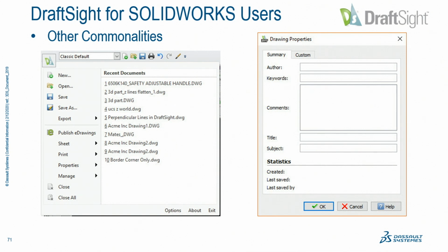What I was going to say about the tables: if you have AutoCAD Mechanical, and you're using the smart bill of materials and stuff like that, currently that does not transfer. So if you want to bring that stuff in, at this point it's going to be kind of a dumb table, you know what I mean? There's something they're working on, but currently you can bring it in, but it's just going to be a dumb table. That's because it's Mechanical, not AutoCAD LT or anything like that. And you notice that they've got bill of material, the Excel stuff, so they are working on that kind of stuff.